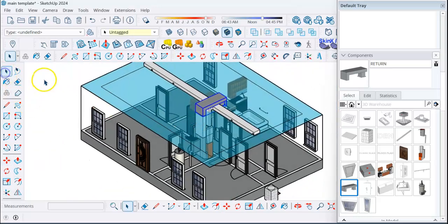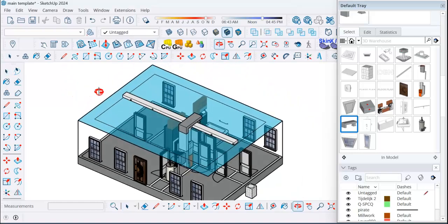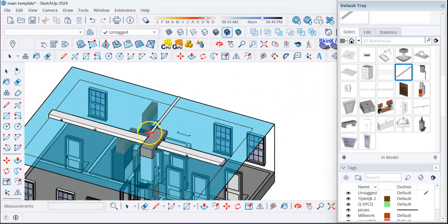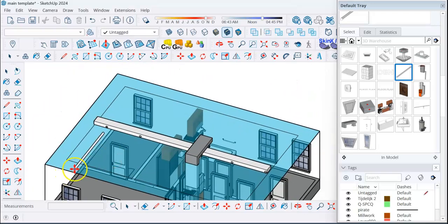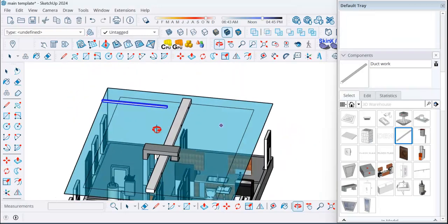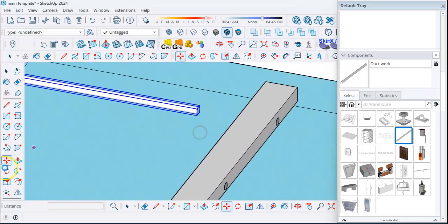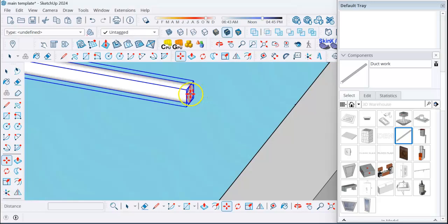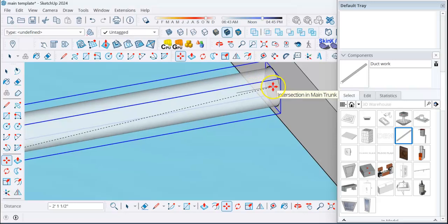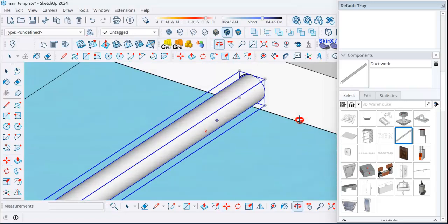Okay, that's a main problem when you're doing ductwork in a drawing, the interference of the different components. The next thing I'm going to do is get a branch duct to come out, which is right there. Isn't that beautiful? And I'm going to just drop it there for now. And I'm going to swing around and grab it by my little point that I have there, and put it at the end of this line, which lines it up nicely with the main trunk.